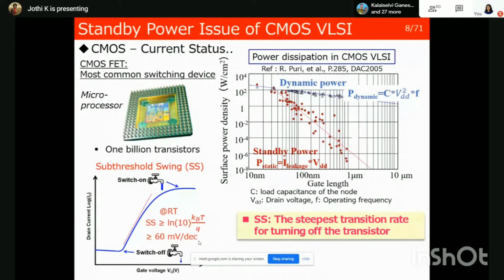But we have to ask the question: why is there always some problem? That's the very fundamental question. In microelectronics, what we refer to is the sub-threshold swing. Some of our people are from Andhra University; in the Andhra University syllabus, they usually show this curve in a linear plot. The current is in linear scale, so you cannot understand much of the physics behind it. In a log graph you can get it: it slowly comes down to a certain value and then remains there.